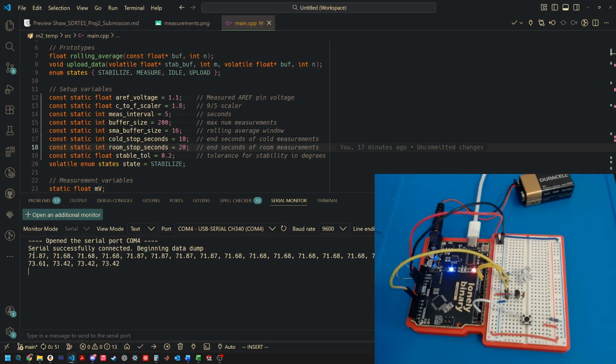Then as soon as we go into our reading, those are comparable in that we have a single LED on during those periods. To try and combat this a little bit, I added what I think is a 10,000 picofarad ceramic capacitor to help smooth out any noise on the power line into that sensor. I think that helped a little bit in some of my experiments, but for the most part, you can still see we're getting about 2 degrees difference for just a regular run.